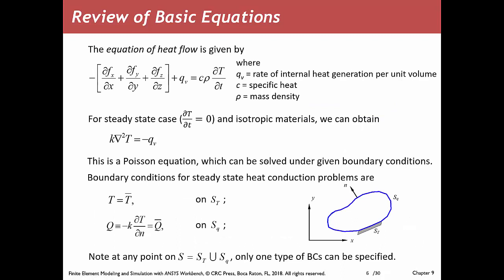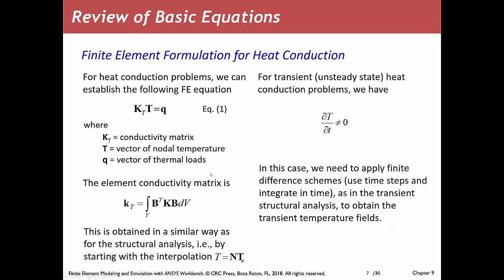Again, this is a formulation that you can read through in the book, but the idea here should remind you of the general finite element equation, M x double dot plus C x dot plus K x equals R. In this case, K is the conduction or heat transfer coefficient, this is the variation in temperature, and this is Q, the heat flux, which represents the external force.